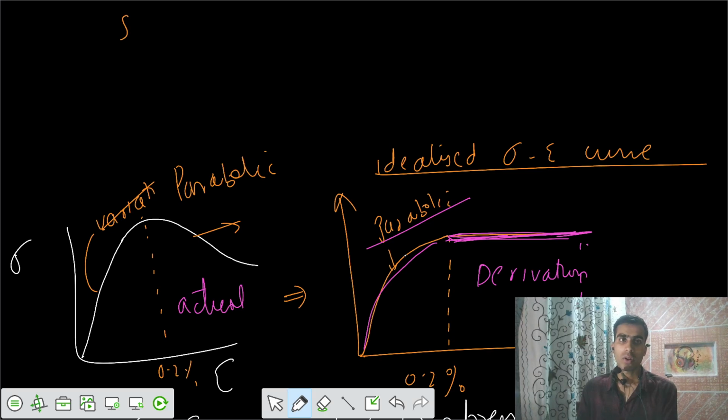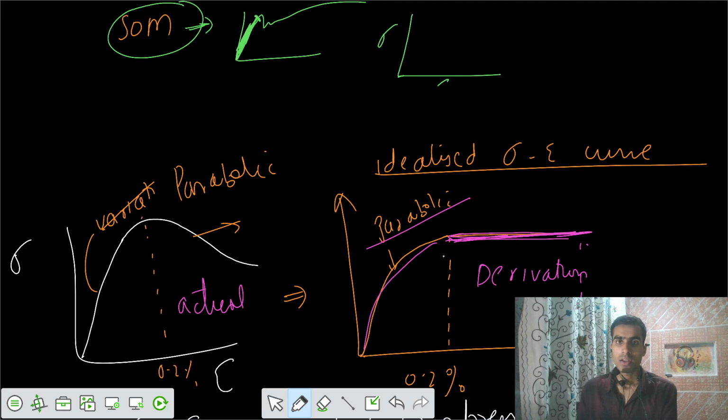See, when we talk about strength of material, that's your structural analysis also. In strength of material, we say that our stresses are below the yield stress. The curve for mild steel was in this fashion, but we say that our stresses are only in this part, the linear part. That means our stress-strain curve is in this fashion. This is our strength of material. It talks about small deformations in the structure, elastic deformation. That means Hooke's law is valid there.